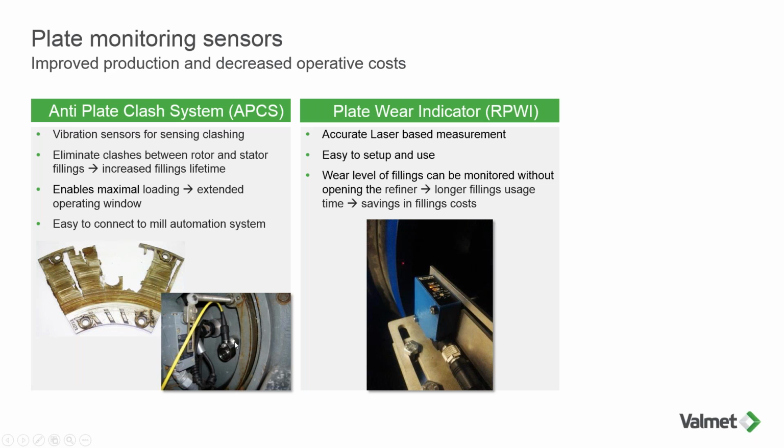And what it is, we have two accelerometers installed, one in each one of the stator positions, and they're measuring axial movement or vibration within the refiners. So every time there's plate-to-plate interaction, the accelerometers pick that up. They're tied back to the DCS. And our logic indicates, hey, let's open the plates up so that we don't continue having plate-to-plate interaction and you're just wasting plates instead of fiber-to-plate interaction. Or more importantly, if there's something passing through the refiner or if the refiner just has no flow through it and you're just plate-to-plate, it's going to avoid a huge catastrophic failure.